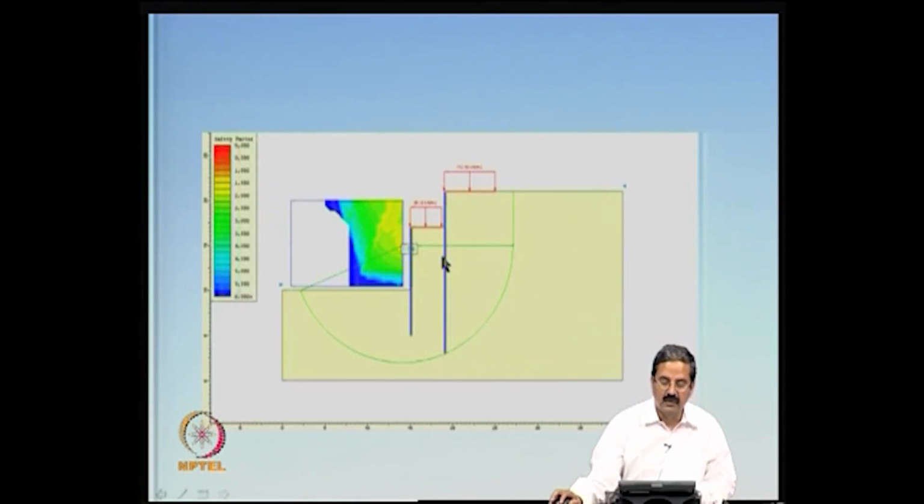So, what I want to say is that one should really understand that micropiles can be designed for their structural capacity as a compression member as well as a tension member, and they can also be designed for shear capacity depending on the situation.